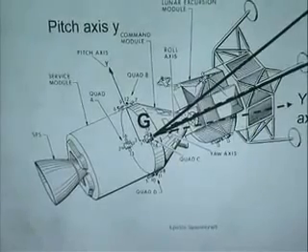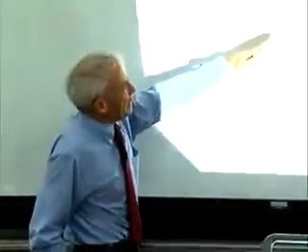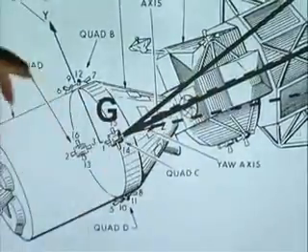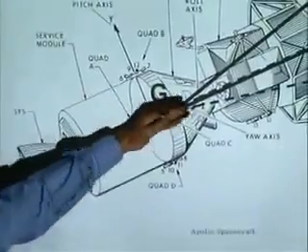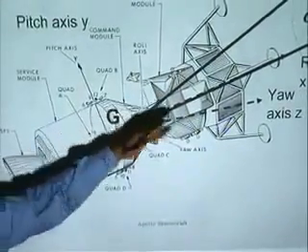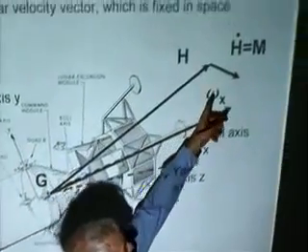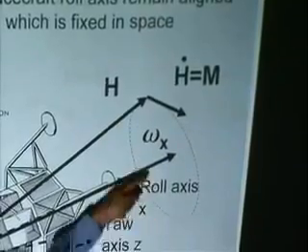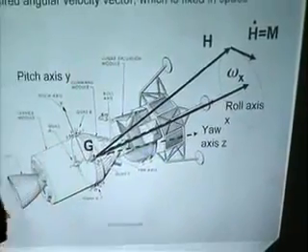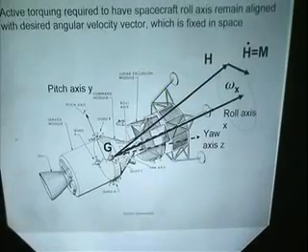And there was a problem. The jets kept firing, and they never were satisfied. We came to the understanding that what was going on was that, because of this being the light axis and these being the heavy axes of rotation, and the principal axis not being aligned here, the angular momentum vector was noticeably away from this desired angular velocity vector. And so it was going to require this amount of continuous torquing to force that angular momentum vector to be coning around in space in order to keep the angular velocity vector in the direction that had been chosen for the barbecue mode. Unacceptable.